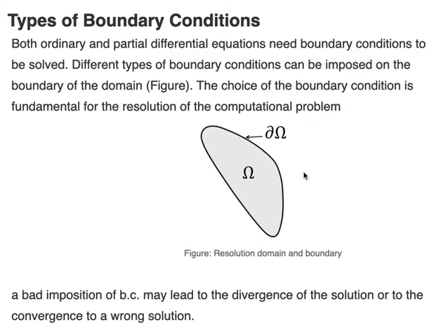The governing equation describes, in the form of an equation, the behavior of the system. It will be a function of the field variable, that is, displacement or temperature, etc., and or its derivatives. It also includes cross-sectional properties, like area and area moment of inertia, and material properties, that is Young's modulus, conduction coefficient, convection coefficient, etc. But the governing equation alone is not sufficient to describe the behavior of the system. So we need to provide additional boundary conditions for boundary value problems and initial conditions for initial value problems. The boundary conditions are of two major kinds.